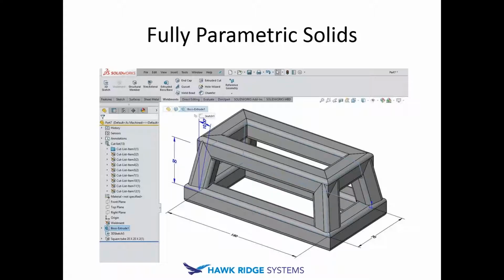There are also two basic flavors of models that can be produced that we'll be touching on, and the first is a parametric or feature-based solid model. So I imagine most people in this room are SolidWorks users. You're probably all familiar with this type of modeling. If you want to change dimensions on the final model, or if you need a model that doesn't necessarily conform perfectly to the scan, but instead reflects the intent of the designer rather than the imperfect reality of the manufacturing process, then this is the way we need to do it.